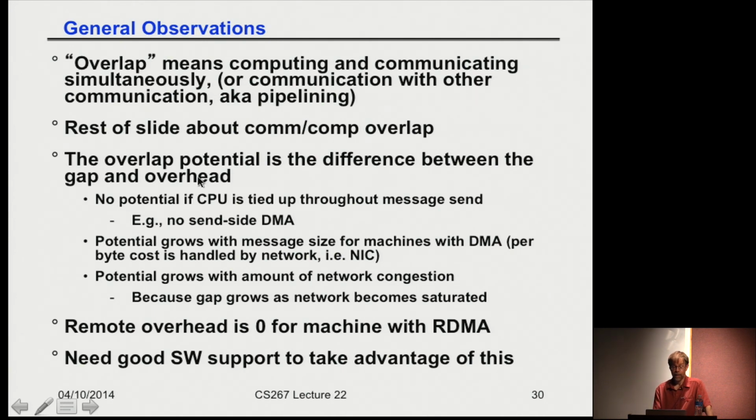And so what does the hardware have to do for this to actually be useful? What I need is what's called send-side direct memory access. I need some hardware support so that I just have to tell this extra processor, here's where my message starts in main memory, here's where it ends, please ship it off.